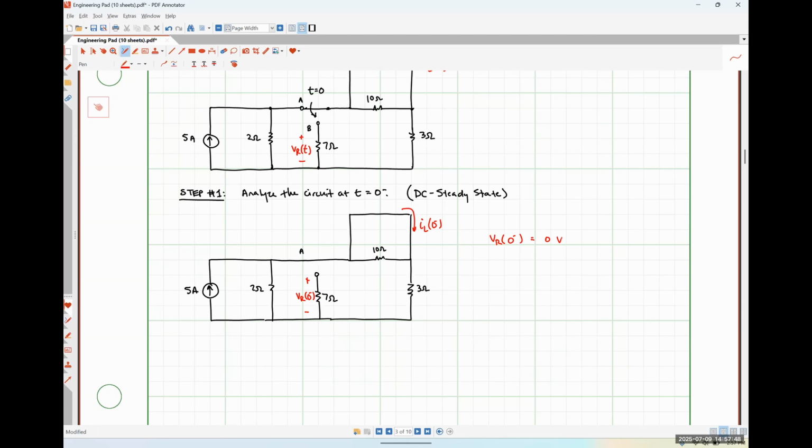Okay. Now, Trevor, I'm going to explain to you why the current flowing through the inductor isn't just 5 amps, right? So essentially, I've got 5 amps that's coming along up to this point right here. And then it sees this path, which contains 2 ohms of resistance, and then it sees this path, which contains 3 ohms of resistance.